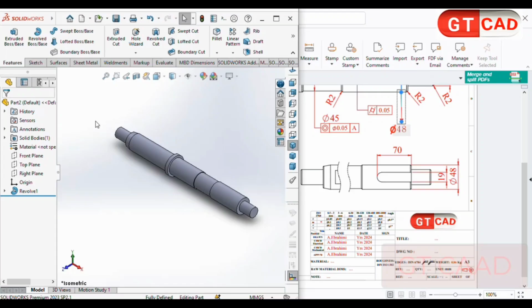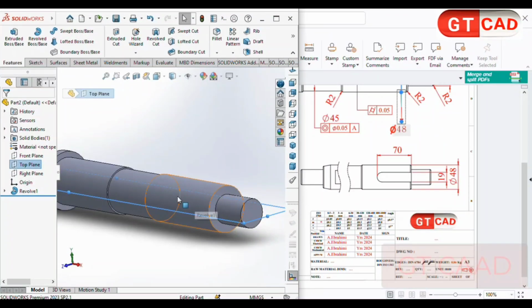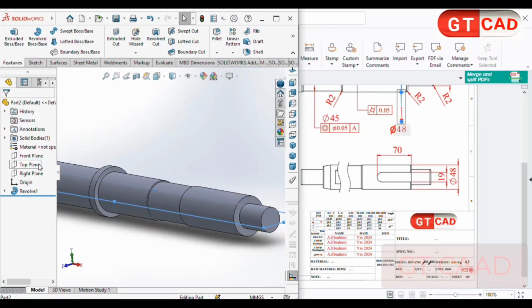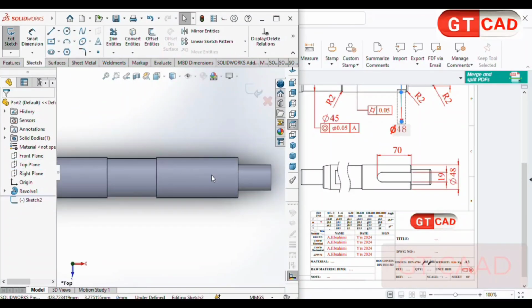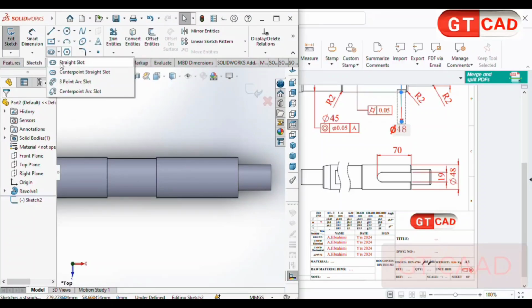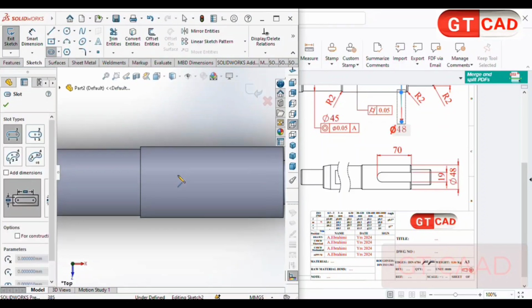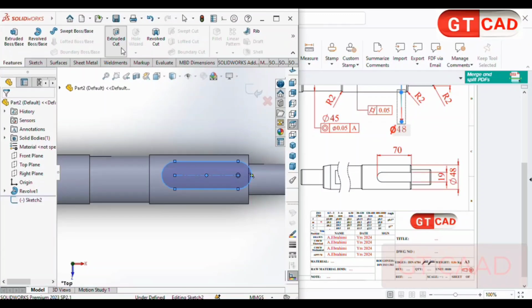In Solidworks, to create any feature, we need to create a sketch. When you create on the top plane and select and create this shape, it started to cut from the middle of the shaft. But I show you two options. Select the top plane, create a new sketch. Our slot to create it is here, this right slot. We have some options, but the first is our goal. For example, create this slot, just drag it here, for example, exit and create extrude cut.